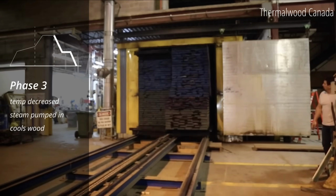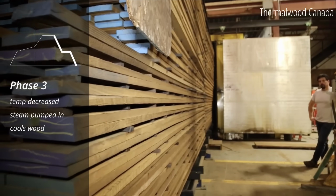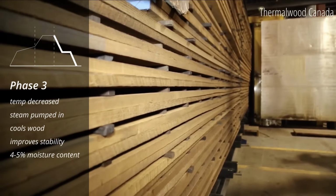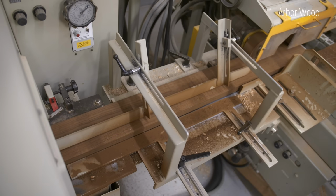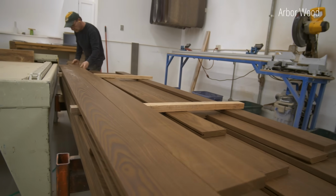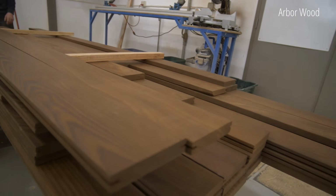This helps cool the wood and increase the moisture content of the planks to improve stability. The average moisture after this phase is 4 to 5%. After the wood planks are removed from the kiln, they are milled down to consistent sizes with tongue and groove joints. Arborwood, a Minnesota-based company, sent me these samples of thermally modified wood for an unpaid, unbiased review.